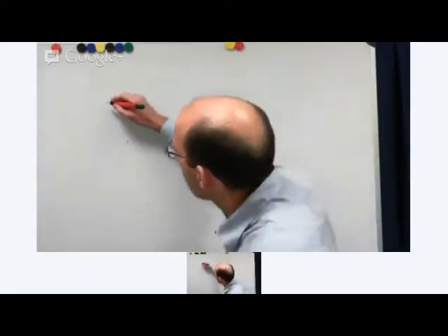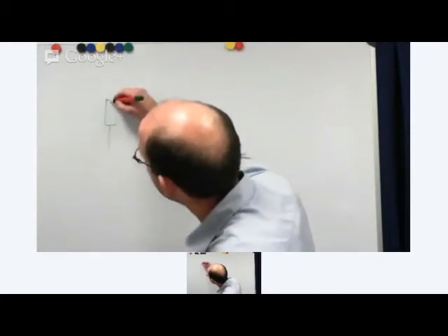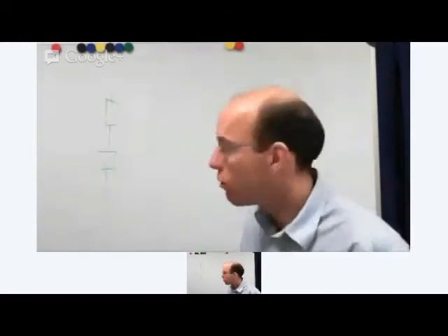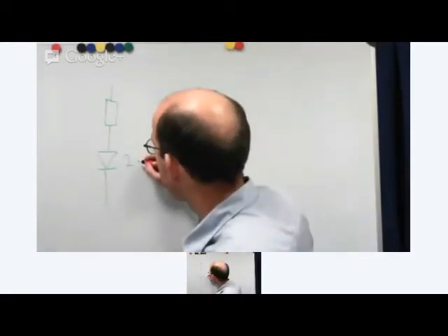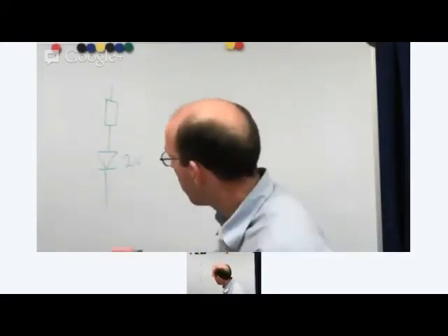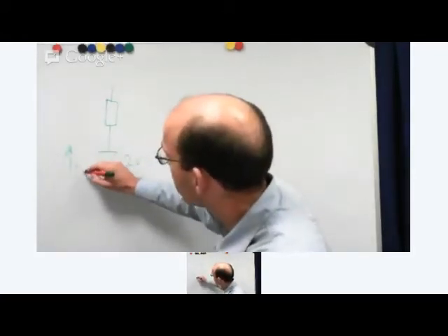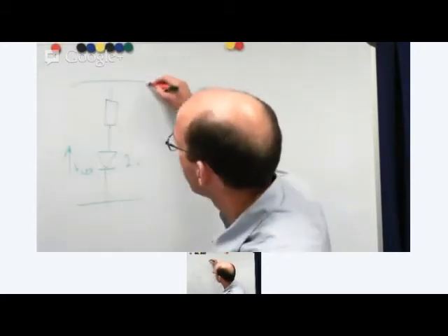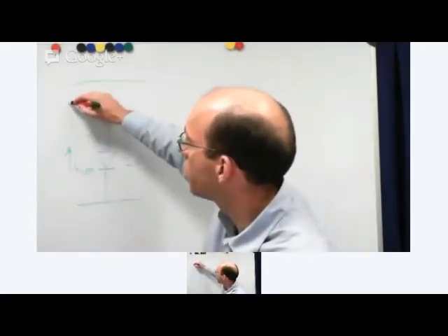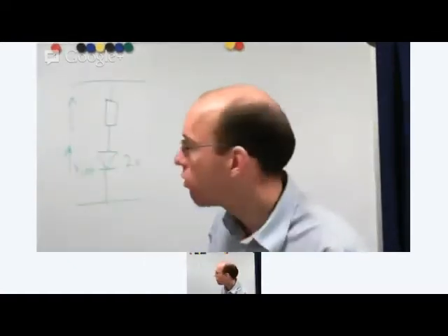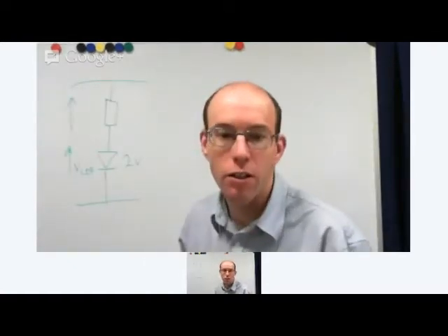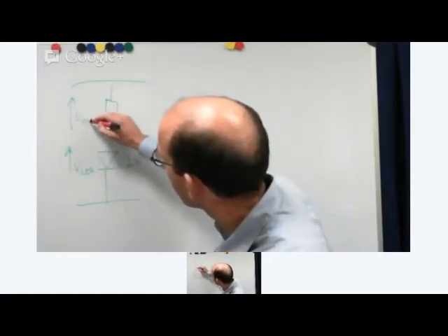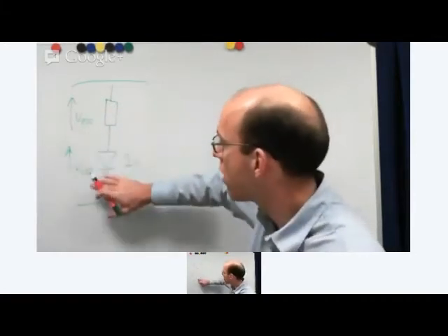So what we do then, we have a resistor and we have an LED. Now typically an LED might have a forward voltage of, let's say, 2 volts to keep the maths simple, and that is called VLED. And then across a particular supply, we're going to have some voltage across the LED, and we need to get rid of the rest of the voltage across the resistor. So we've got V resistor there and VLED there.